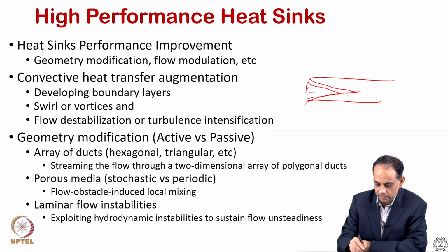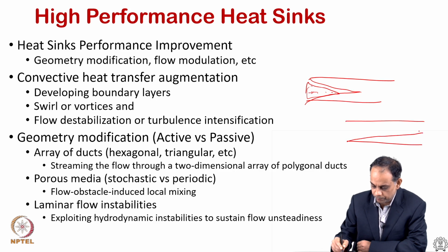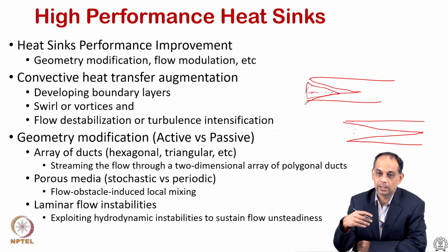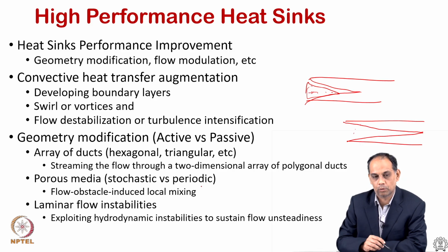That means it is still at the incoming temperature, and the boundary layers merge, especially if they are merging right at the exit, as we discussed in the previous lecture. Now this area is underutilized. How can we utilize it? Because this is stratified, with colder flow and warmer flow, if we can mix both of these streams, then we may end up getting more heat transfer performance, and that is achieved through introduction of porous media or any flow obstacle in the flow stream.